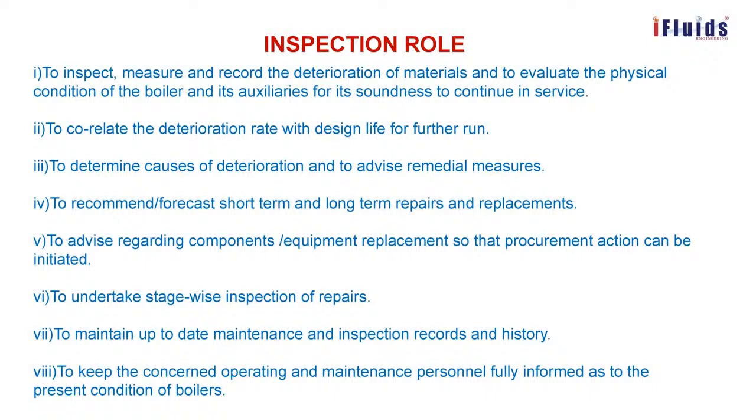The basis of this inspection is to estimate the run length of the boilers and the envisaged problems, and what components or spare parts have to be bought. For that, the lead time has to be calculated, and based on that, everything has to be arranged for the next shutdown. These are the main actions of inspection.